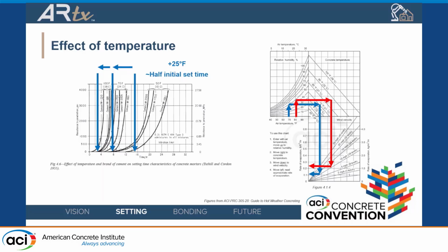The hotter it is, the faster we evaporate, and the drier it is in the air, the faster we evaporate. So slight changes can actually really change the evaporation rate, particularly if it's windy. And both of these actually affect the penetration resistance. The evaporation and that interaction with the ambient temperature at the surface of the bead actually causes, in some mixes,